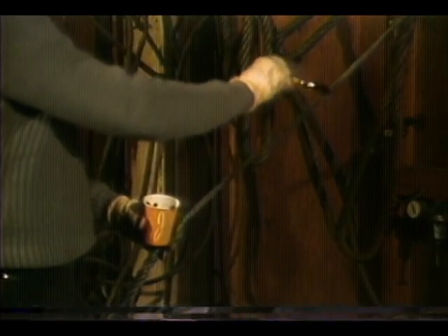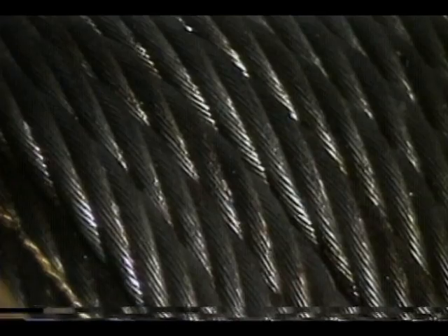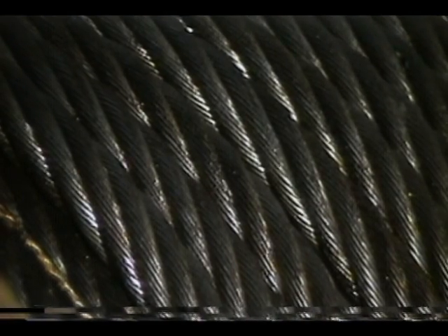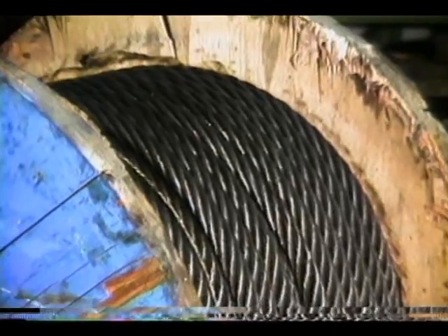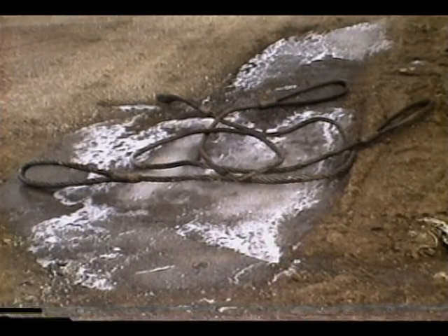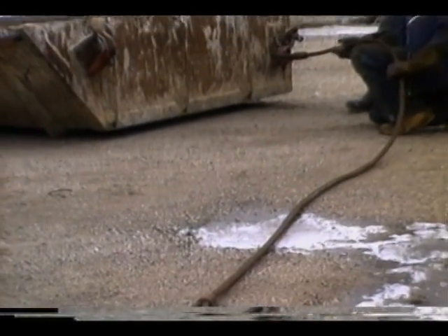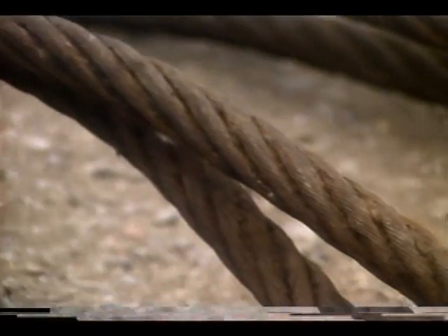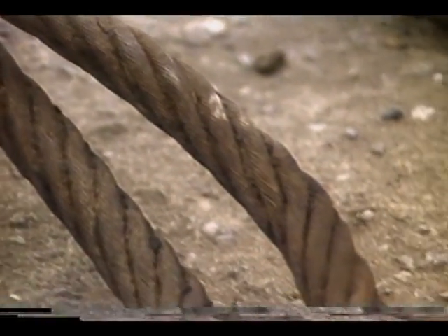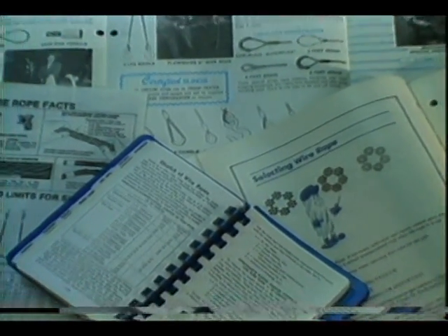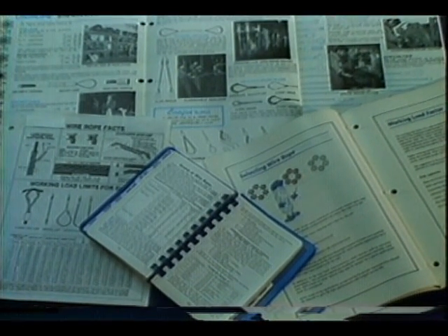Lubrication is the prime factor in extending the working life of wire rope. Lubrication not only reduces friction between individual wires in a rope, it can also prevent internal rusting. Most wire rope is lubricated before it leaves the manufacturer. But even well-lubricated wire rope should not be unduly exposed to the elements. Wire rope exposed for long periods of time should be checked frequently for damage, corrosion, and possible breakdown of lubricant. Wire rope should be cleaned and lubricated regularly, according to the rope manufacturer's recommendations.